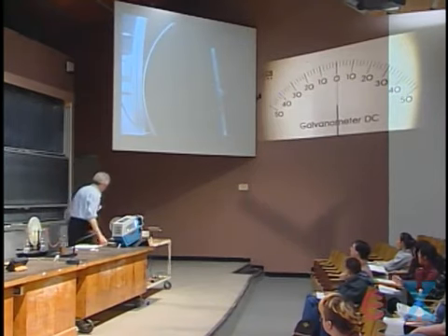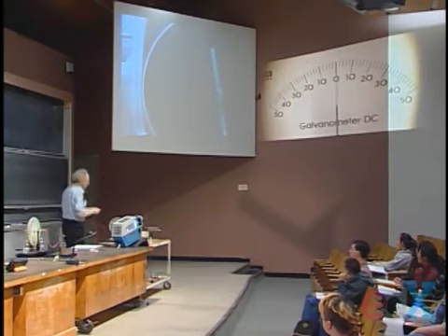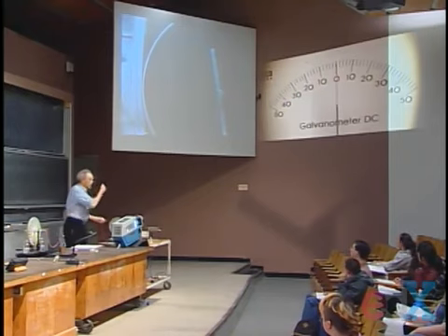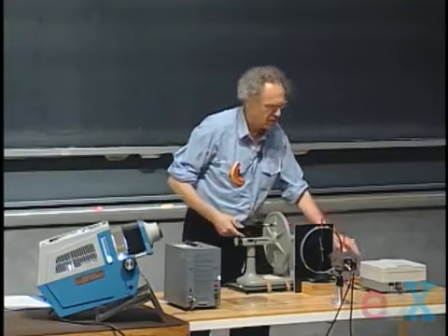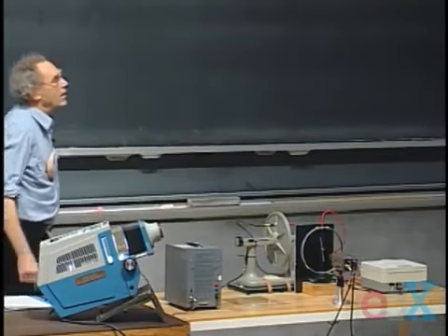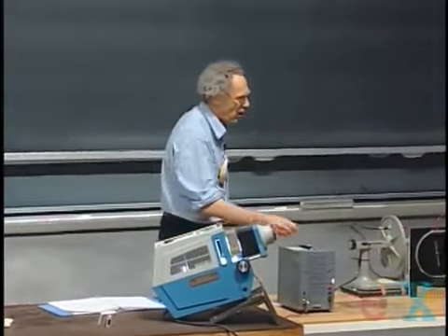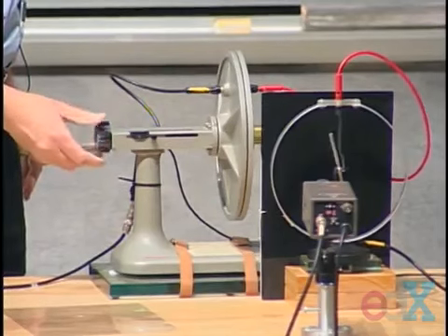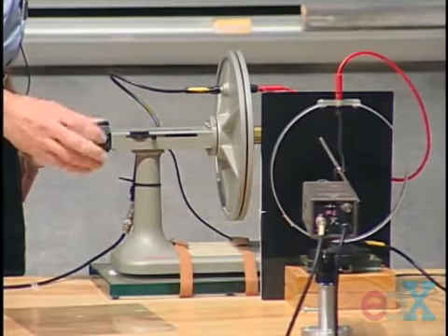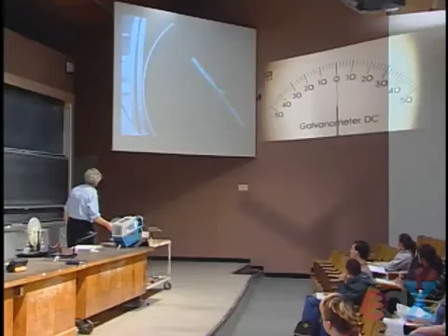And I'm going to charge the plates. I will count down, so you keep your eye on the ammeter. 3, 2, 1, 0, and you saw a current surge. So I charged the capacitor. It is charged now. The voltmeter doesn't show very much, 1500 volts. Maybe it went up a little, but not very much. But now I'm going to increase the gap to 7 millimeters, and look, the ammeter is not doing anything. The charge is trapped, so there is no charge going to the plates.